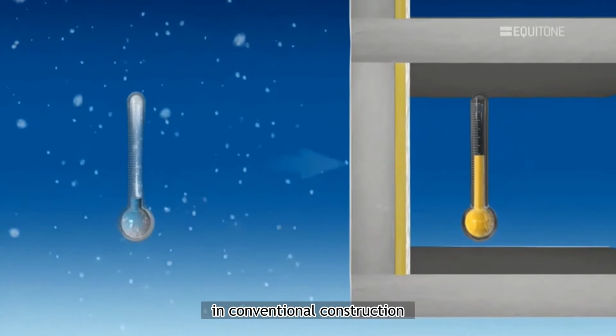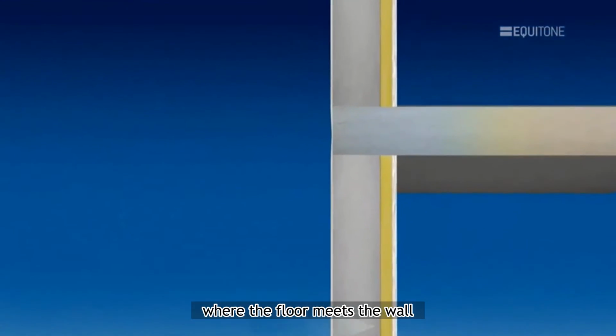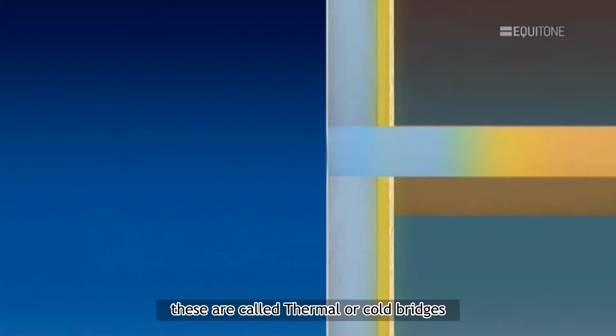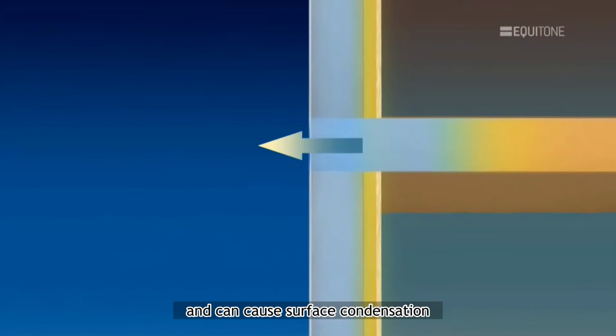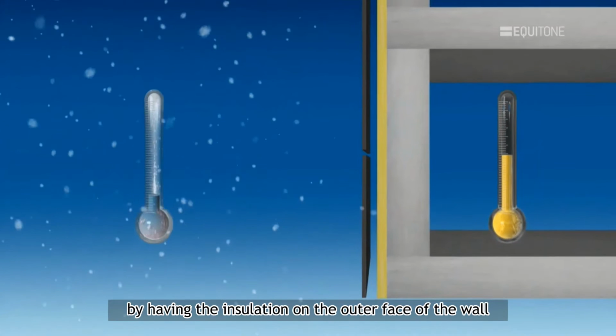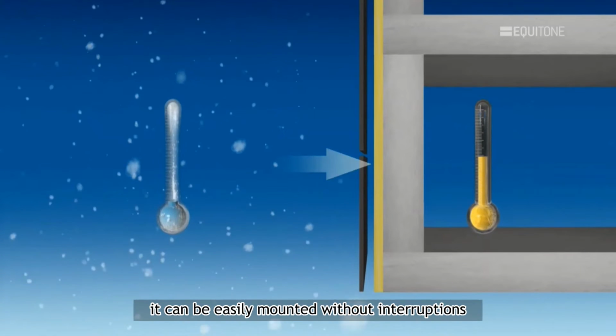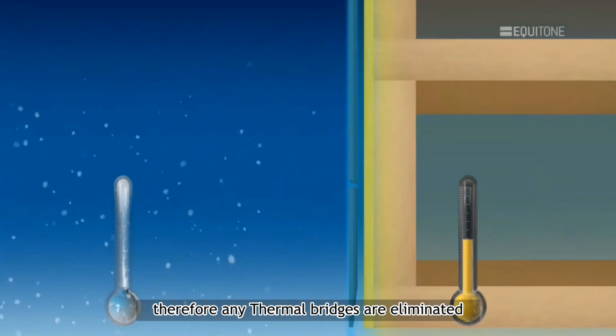In conventional construction with internal insulation, the thermal shield has weak spots where the floor meets the wall. These are called thermal or cold bridges. This results in heat loss and can cause surface condensation, which can lead to mold growth. By having the insulation on the outer face of the wall, it can be easily mounted without interruptions. Therefore, any thermal bridges are eliminated.